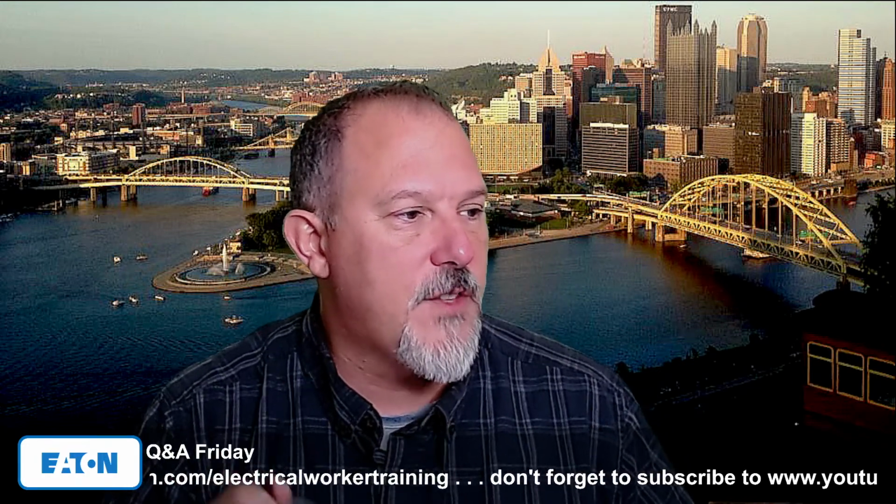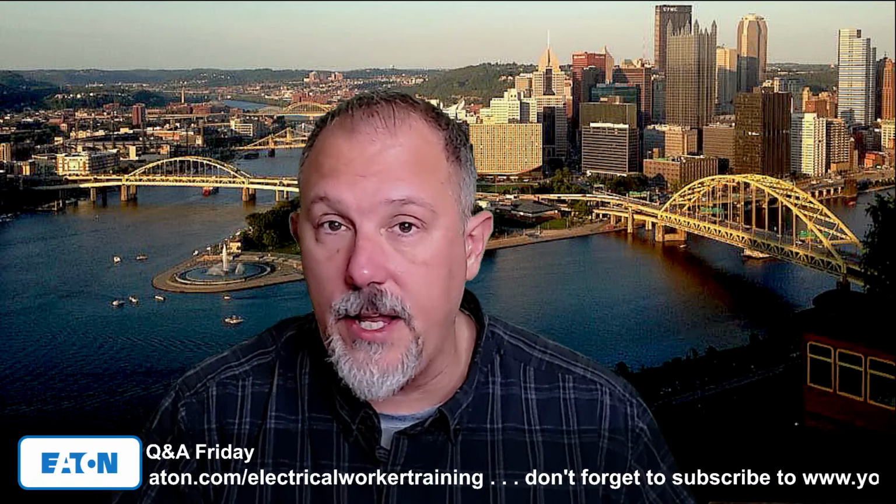Here's a reason not to use 3-phase panels on a single-phase application. If someone accidentally puts more than one 2-pole breaker in and has one stab connected to the unused phase, it will create a circuit with the same voltage irregularity problems that can exist with an open neutral. Very good point, JW. And this was a question with regard to the comment of using a 3-phase panel in a single-phase application. Was there any code that says you can't do that? And no, there wasn't any code requirement that says you cannot do that.